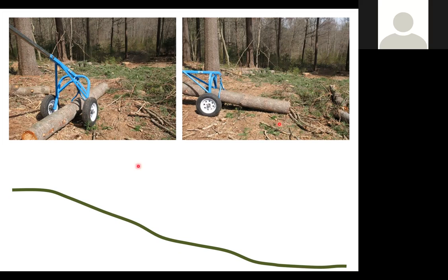Now, if you're combining the arch with an RTV and you're headed on a downhill skid, this is going to create a problem for you. The brake system in the RTV is designed to hold back the RTV going downhill. This is a lot of mass for that brake system to try to hold back. And so I would clearly caution people, as tempting as it is to lift that log off the ground and go off with it, you don't want to have this kind of mass pushing your little tiny vehicle downhill. You'll lose control very